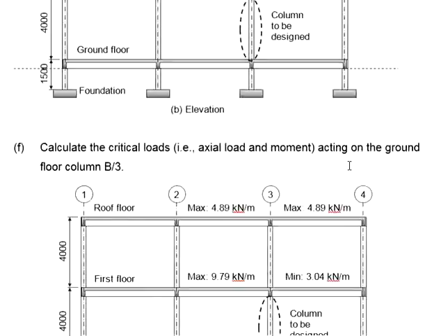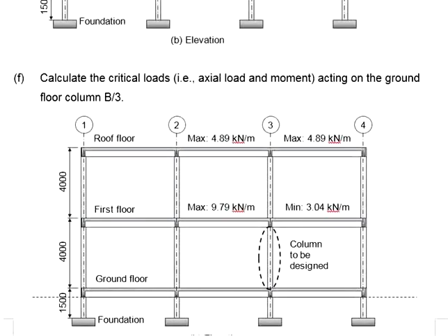The calculation is based on simple assumptions, assuming the beams are simply supported over two columns at both ends, and the loads will be equally supported by both columns. Such an assumption may not be accurate, but theoretically it should not deviate too far from the actual loads. We made such an assumption because we want to make the calculations simple, especially for manual calculations, trying to make it as simple as possible.